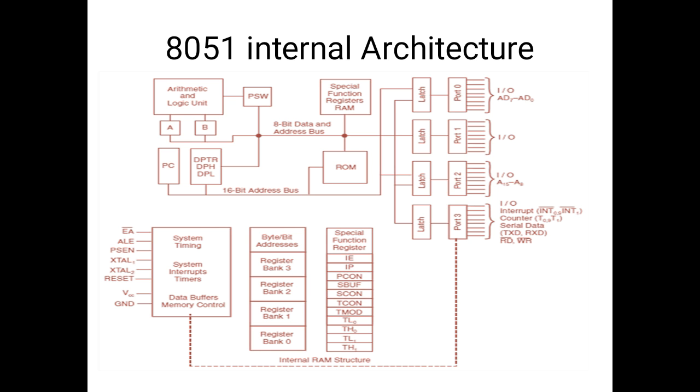There are two pins shown below, XTAL1 and XTAL2. This defines the clock circuit. It uses the crystal oscillator circuitry to provide the clock. The 8051 can work on 1 to 16 megahertz of clock frequency, which is provided through the inbuilt oscillator.